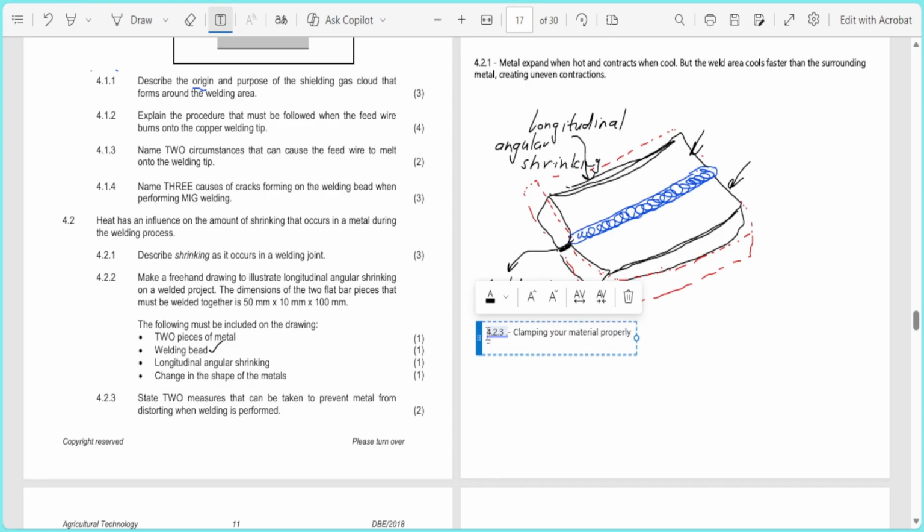Okay, and doing some presetting. I can go, as well as maybe something like spot welding. It's gonna work. All right. So the presetting simply means that we are deliberately positioning the pieces slightly off, right, so that the shrinkage pulls them into alignment. So we are purposely misaligning them, right?